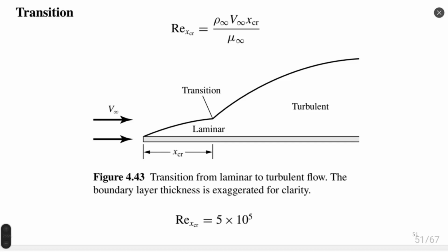This transition depends on quality of surface, can be turbulence inside incoming flow, and I think temperature influences a lot on this distribution because viscosity is also changing significantly with change of temperature. So there are several parameters influencing the transition process from laminar to turbulent. And another limiting factor for us is thickness of boundary layer. When these two thicknesses are the same, transition happens.